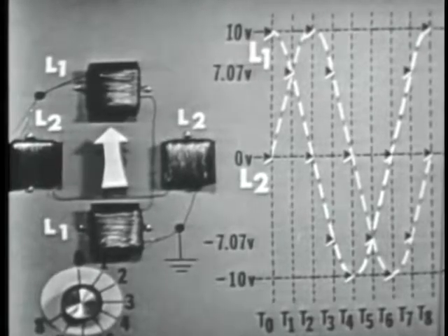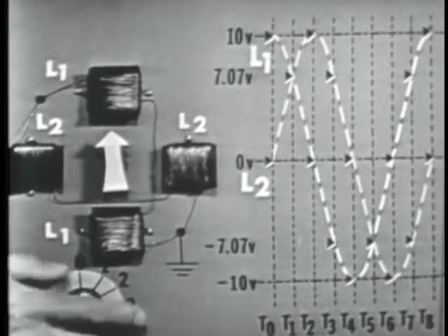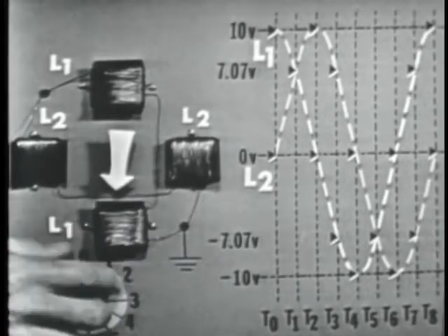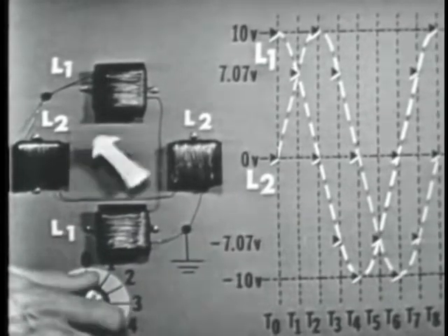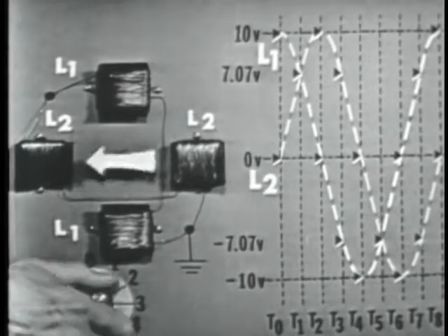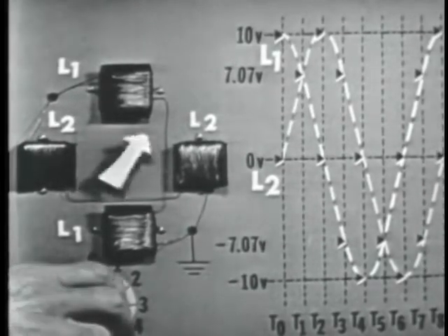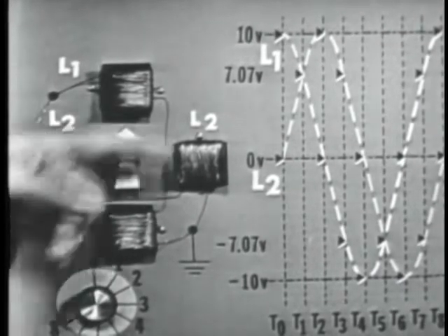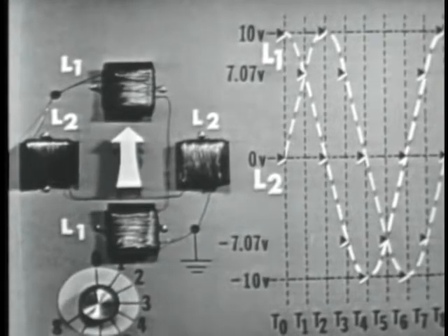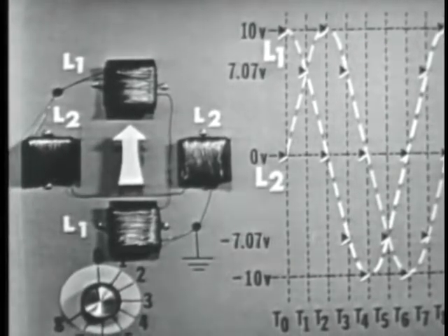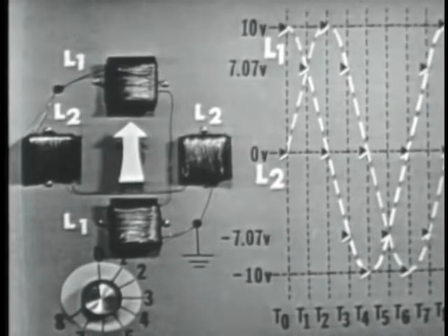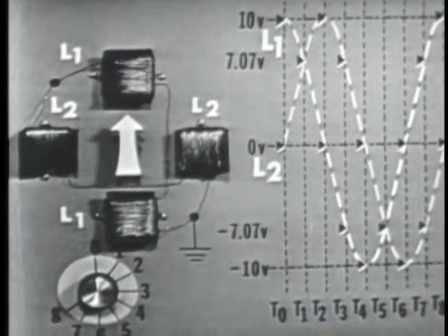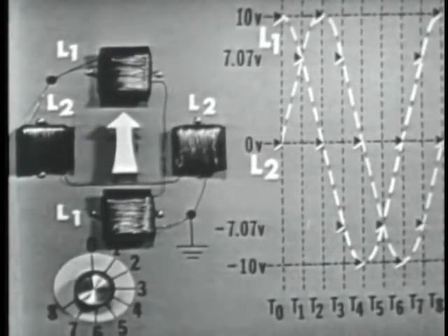All right, you can have it. Item 7 shows you how one complete revolution of the magnetic field is accomplished by applying these out-of-phase voltages to the stator windings. Now, you can study this very, very carefully so as to fix the principle in your mind. And, by the way, we might point out, Tom, once again, that you can apply the left-hand rule to all these coils and prove precisely what we've said, right? We can develop a rotating magnetic field. I'm certainly glad you said that, a rotating magnetic field that induces a voltage in the rotor, causing it to become an electromagnet, which will follow the rotating magnetic field.